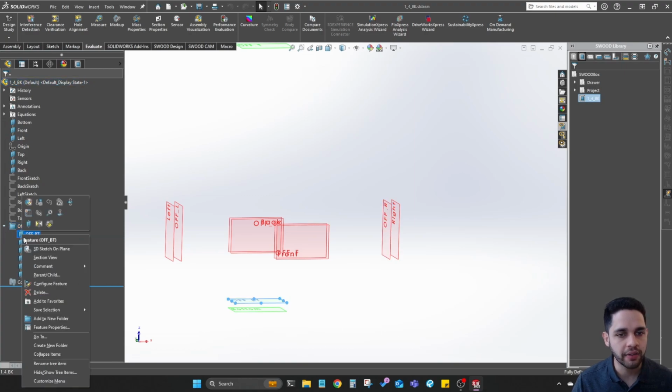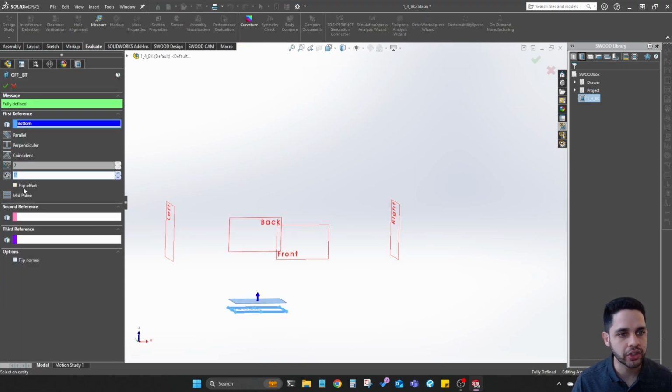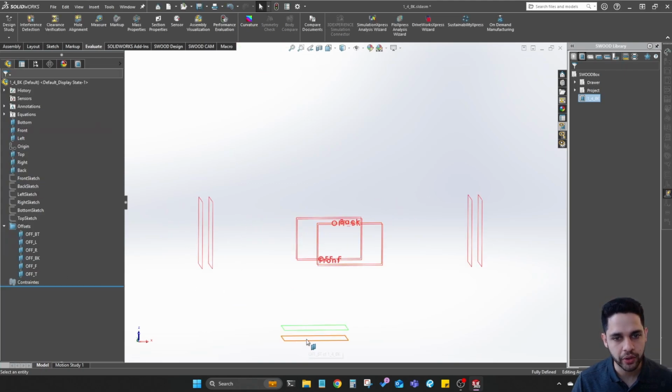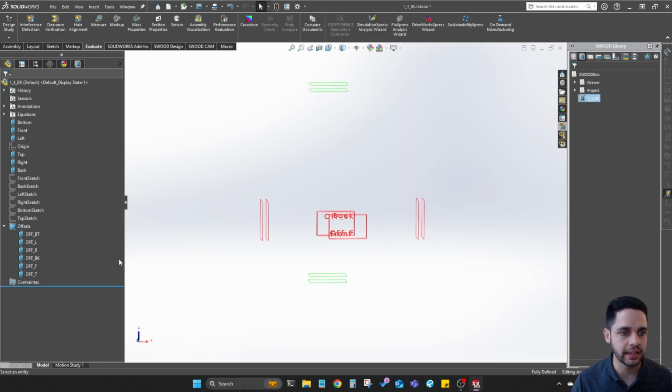So all of these offsets, I want to switch their offset. Because if I kept it like this, it wouldn't dado into the box, but I do want to dado into the box, so I'm switching that offset, and that'll allow that panel to do so. I'm going to do that for the bottom, the left side, right side, and top. So let's go ahead and do that.